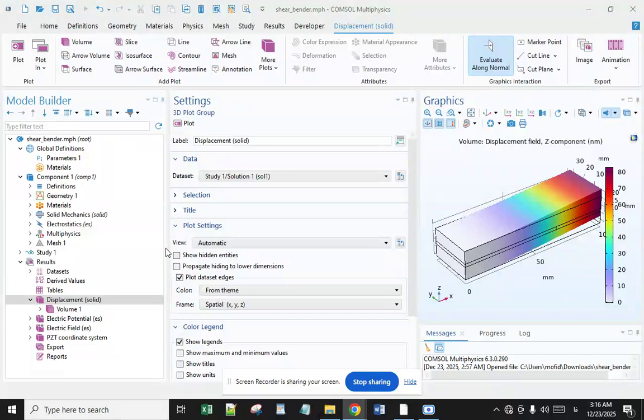A first adaptive sandwich beam model was developed in previous works, and due to the presence of shear locking problems in this element, a second model with a different kinematic description was developed here. This second adaptive sandwich beam model, taking into account the extra shear due to the sliding of the faces against the core, also allowed a better understanding of the energy dissipation capacity of the beam.